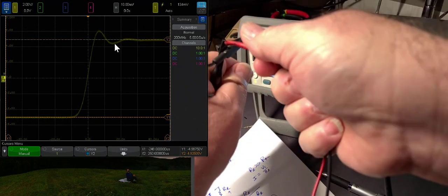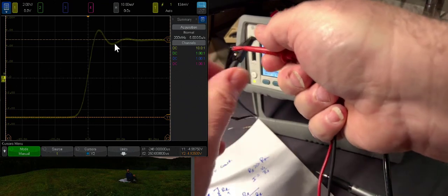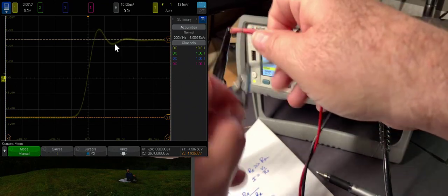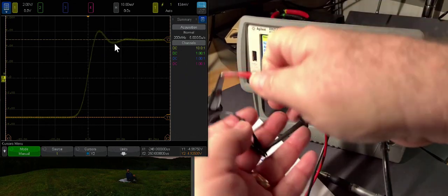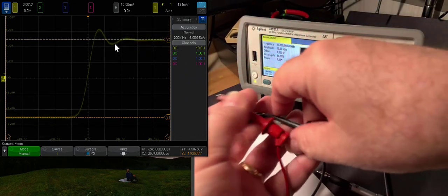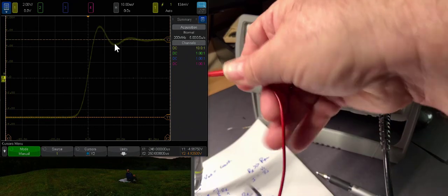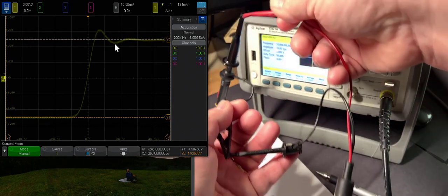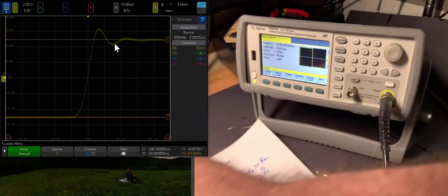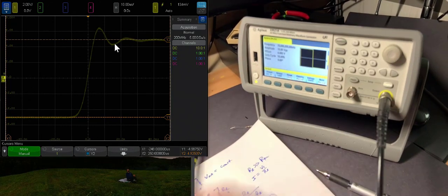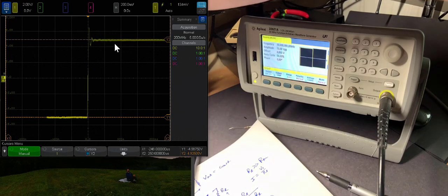Look, I'm affecting that signal coming out. I can change the shape of the loop, and I will adjust that ringing that we see. Now, for now, it's okay. We'll figure out a way around that later. But you can see that the geometry of that loop, the physical interconnects, are affecting that signal. For now, that's okay, because we're looking at mostly the DC level.